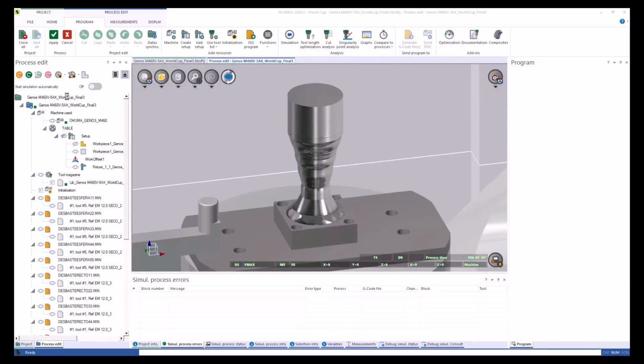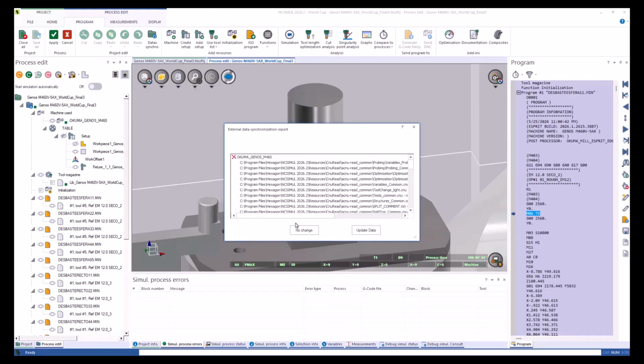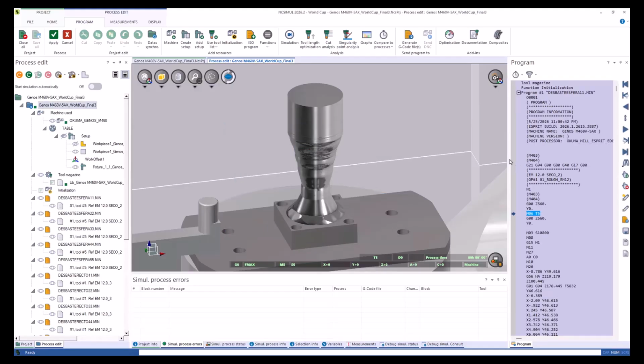So let's open this project and let NC Simul decode the G-code as normal, your normal process that you've known all along. This is in accordance with our classic three-step process, but is isolated to parsing through the G-code. This is still useful when initially analyzing the program for syntax errors, but in a case like this one that has really heavy machining, we want to create jumping-in points to isolate those high-value machining processes for you.